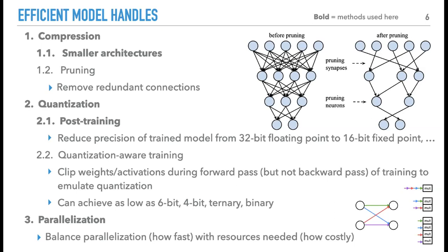The model is trained in 32-bit floating point, and you just reduce it to something like, for example, a 16-bit fixed point representation for running on the FPGA. And what we find is, in general, as long as you have enough bits, this post-training quantization works pretty well, and lets you reduce the number of bits you need for the computation.